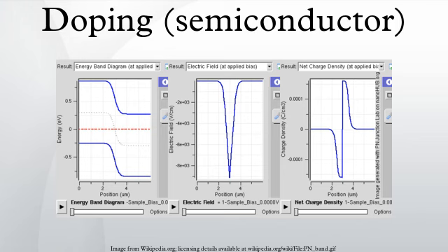By doping pure silicon with group 5 elements such as phosphorus, extra valence electrons are added that become unbonded from individual atoms and allow the compound to be an electrically conductive N-type semiconductor. Doping with group 3 elements, which are missing the fourth valence electron, creates broken bonds in the silicon lattice that are free to move. The result is an electrically conductive p-type semiconductor. In this context, a group 5 element is said to behave as an electron donor, and a group 3 element is an acceptor. This is a key concept in the physics of a diode.